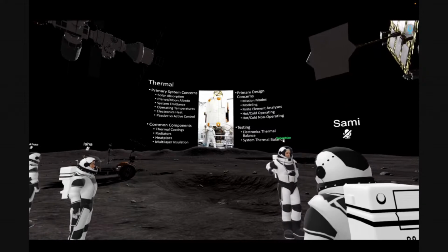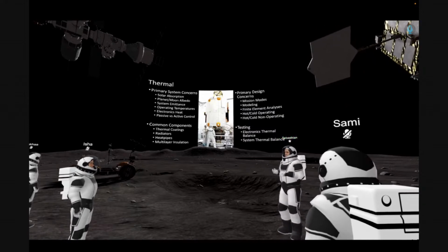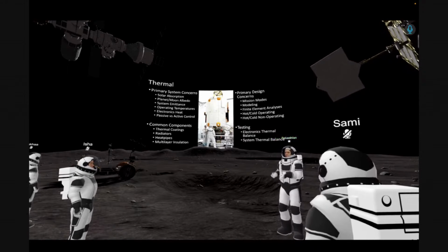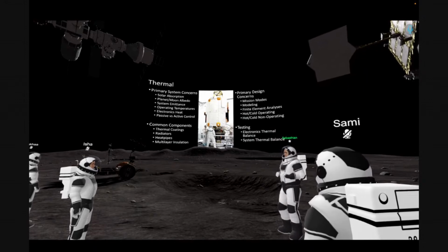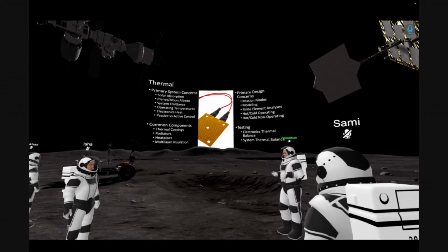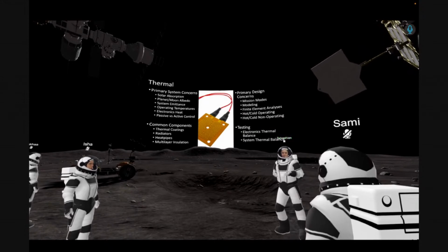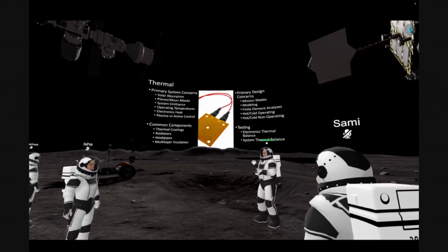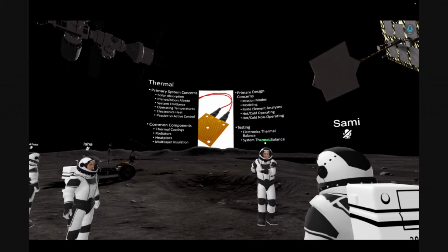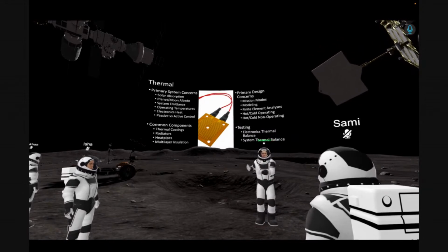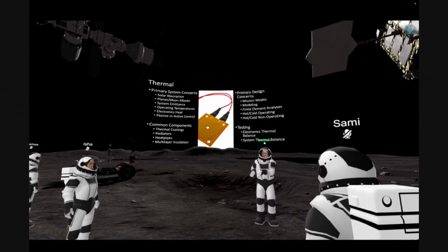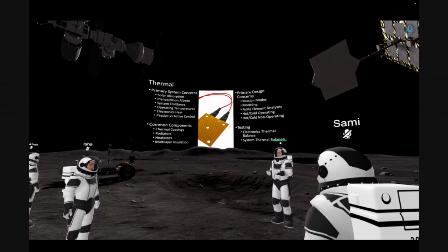And it happens exactly the same with the satellites. They stop working if you expose the electronics to the wrong temperature. So you have two options. Either you protect them from high temperatures, so the temperature doesn't go too high, or you take care of the temperature inside by adding, for example, heaters. This thing that we're seeing now in the presentation is a heater. So you apply electrical energy to this device, and it starts getting hotter. Okay, so you can put that on top of your circuits, for example, and you can be sure that the system will be in the operating range of the satellite. In that way, we can make sure that it works.